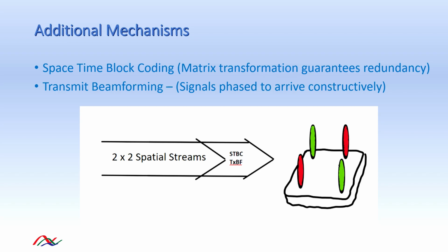But it's possible for a client with 2 antennas to drop the spatial streams and use either STBC or transmit beamforming to improve its signal to the AP. So depending on the specification and features of a client, it may be possible to use these enhancements to improve an AP's reception of weak client signals, which would be one of the more useful use cases for these technologies.